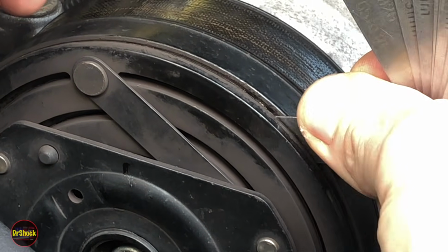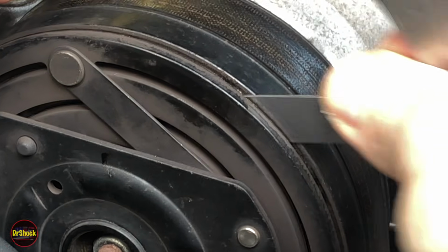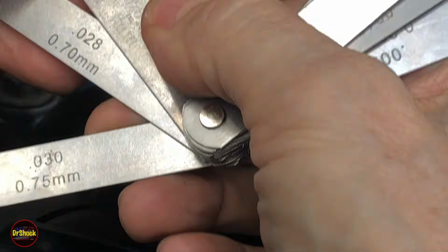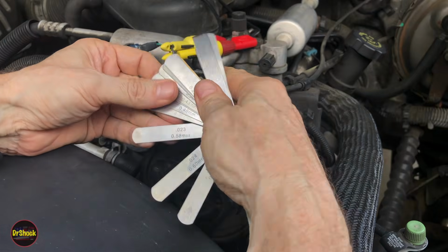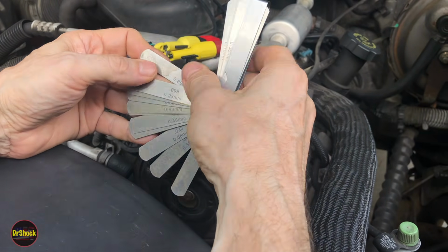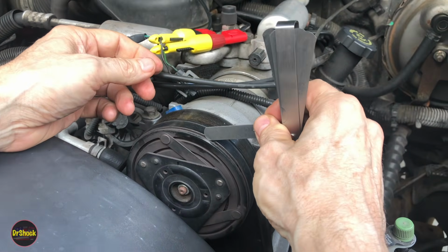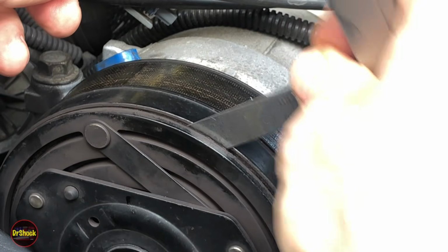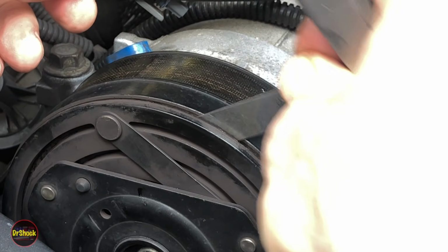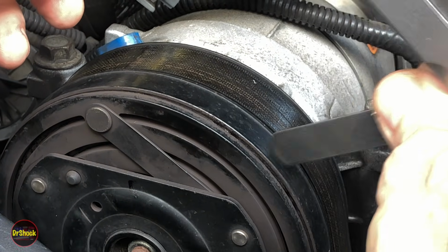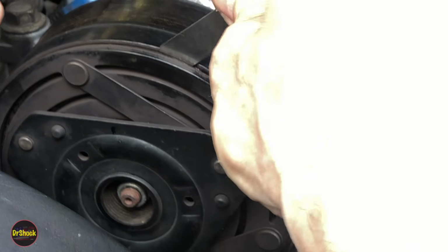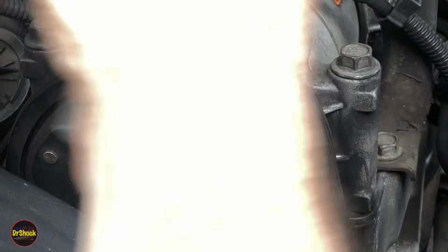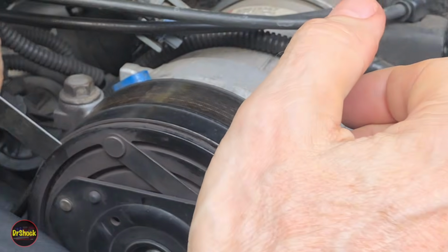All right, so if that's the biggest that fits in here, then we're fine. But if I try the next size up from that, which I believe I've got a 32 in here. Let me find him. There he is. I got a 32 in here. And this 32, he's a little bit more snug, but he still fits. Fits real easy on this side. Fits really snug on the top, and you can get uneven wear situations with these clutches.